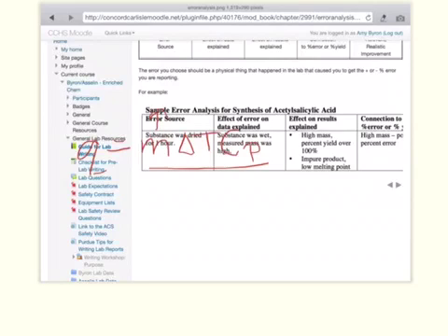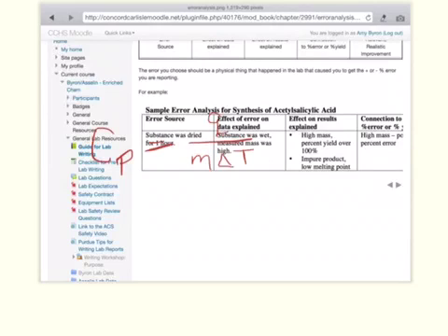This would make more sense: Cp equals Q over M delta T. So if your mass ended up being too high, this is just an example. You should not use this as an example, it's a really bad example. If your mass was too high, what that would mean is your denominator got higher. So Cp, your specific heat, would end up being lower than it should have been.